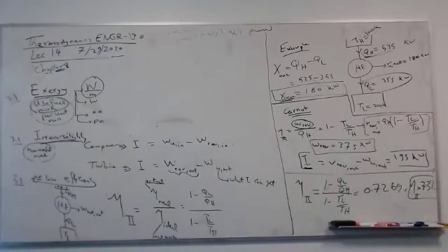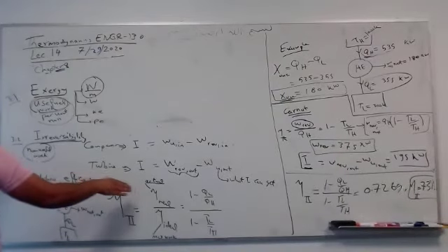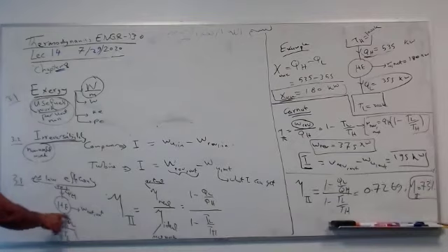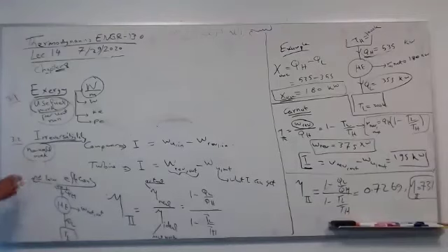Exergy: useful work, the more the better. Irreversibility: a measurement of non-useful work, how many losses are in your system. Second law efficiency is the efficiency of real over efficiency of ideal. Ideal is Carnot, which has maximum work. So Carnot is always the max efficiency. If you are comparing, for example, a Rankine cycle, compare Rankine to Carnot. Carnot is when you talk about T low and T high. When you go by T high and T low, this is the maximum efficiency. But if you talk about Q low and Q high, now we are in between. You have a little bit more losses. You have some non-useful work.